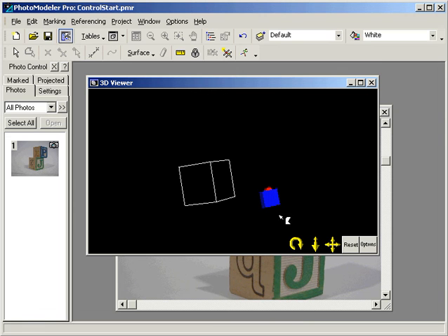We have solved for the camera position and the 3D data provided in the control point file. For a particular type of project called camera perspective matching, this result is all that is needed from the project. In perspective matching, you have some known XYZ data of an object, and you're just trying to solve for the camera's focal length and its position. This type of project is used often in the film and animation industry.